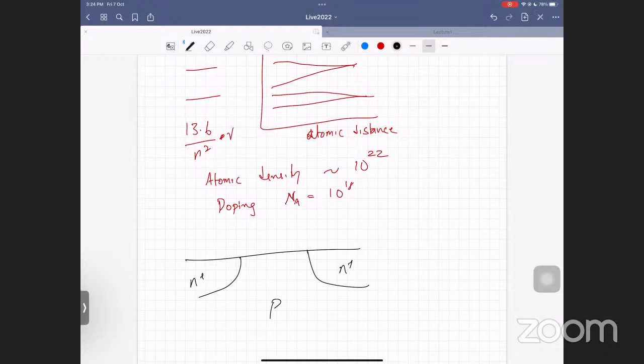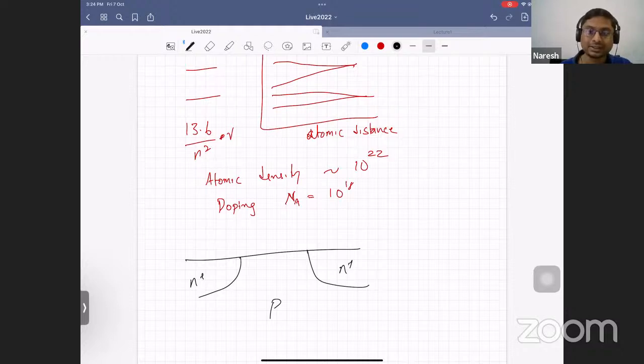Doping is only, Kushagra, okay. Yes, the processes that you're referring to are only for doping the wafer entirely. When you make a MOSFET, you have to dope only certain regions in space, right? That is usually done by what is known as the implantation process, or in the olden days, it was diffusion. But diffusion has some limitations, so let's not get into all that. Implantation is a technique that most of them use.